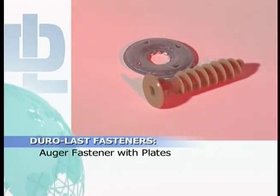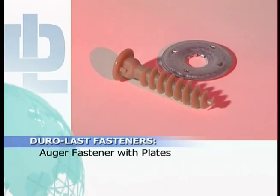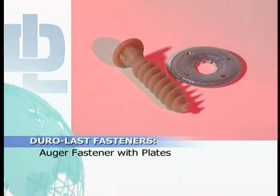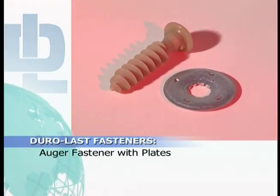The auger fastener will bore through the tectum without a pilot hole. If there is an existing built-up roof over the tectum deck, pre-drill through the built-up roof only.